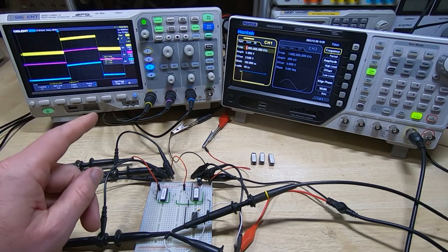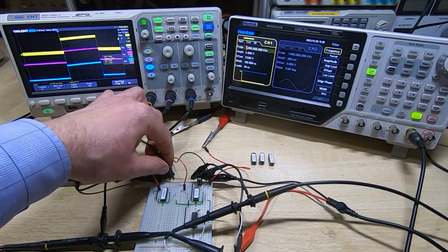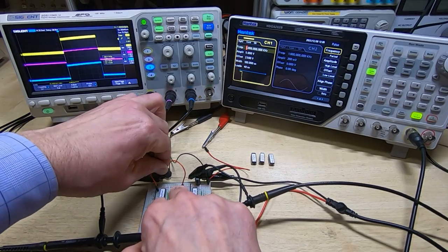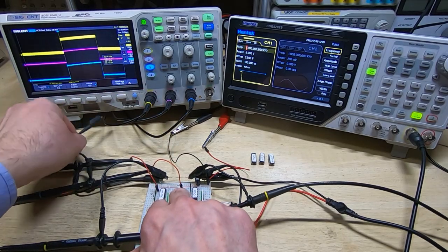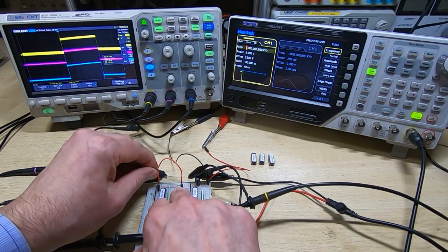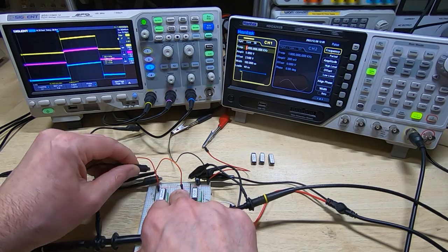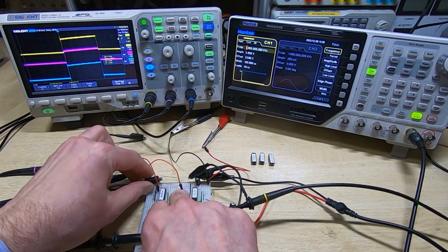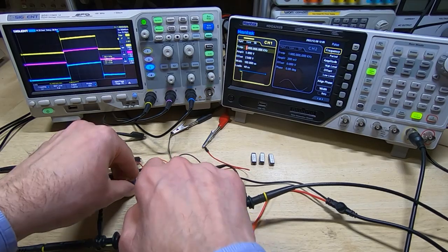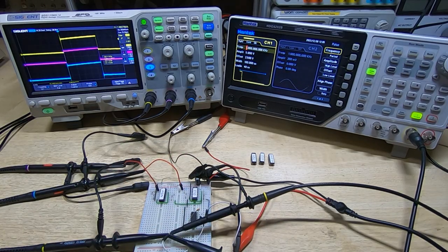And what I'll do now is disconnect the ground leads so you can see what effect that will have. So we'll disconnect the first one. Now, of course, these are all connected to the same scope. So long as you have one connected somewhere, then it's going to be a valid ground path. So let's get the last one off. So as you can see, it has almost no bearing on the signal at all.